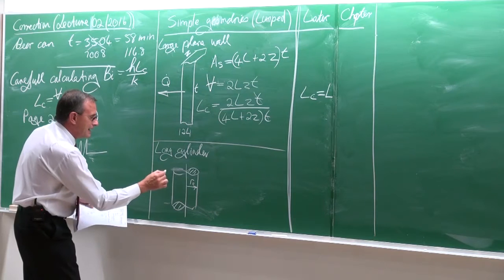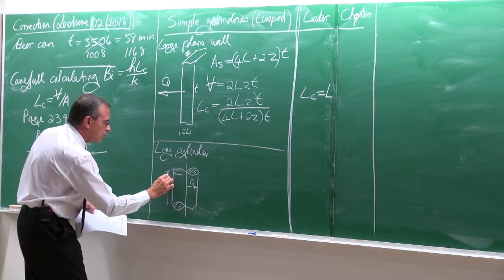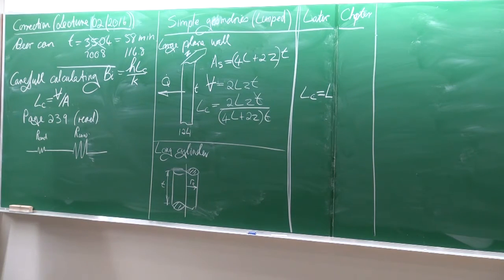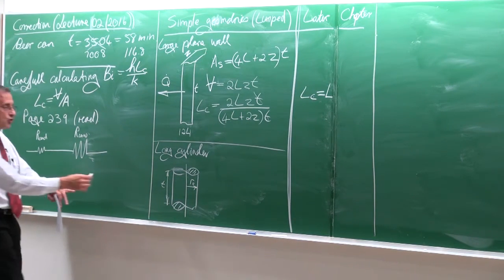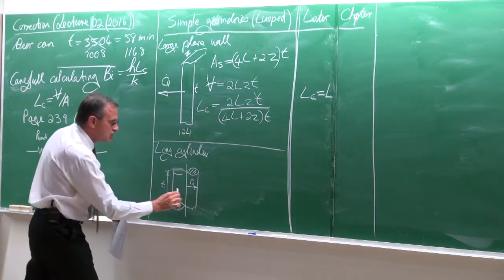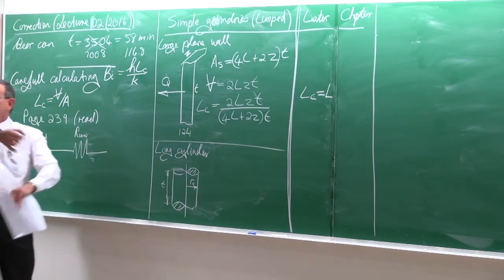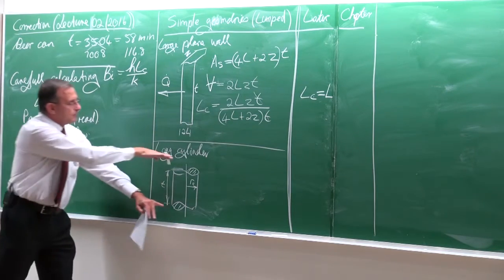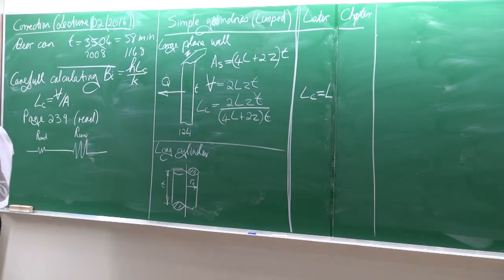And we can choose any length there. T can be 1 meter or 10 meters or 100 meters. It doesn't matter. Again, the heat transfer is only in the one-dimensional direction. It is not in the axial direction. That heat transfer is negligible or it is insulated.